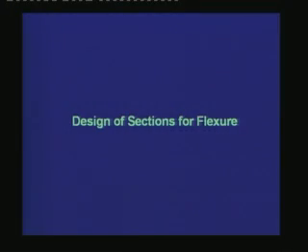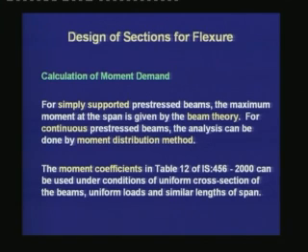Next, we are moving on to the design of sections for flexure. Now, for flexure, how do we calculate the moment demand? For simply supported pre-stressed beams, the maximum moment at the span is given by the beam theory. That means we have the expression from the beam theory of the maximum moment that comes at the span.